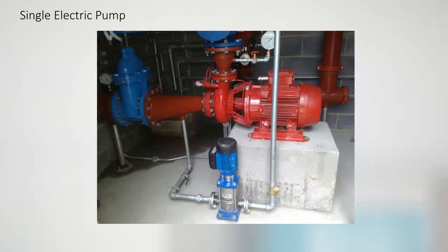However, if the pump kicks in without a sprinkler activation, you don't want to cause a false alarm. So you need to put in a signal from the pump and a signal from a flow switch. But I would recommend that if you have a pump activation, that it's sent off-site to an alarm receiving centre, just so that they can inform